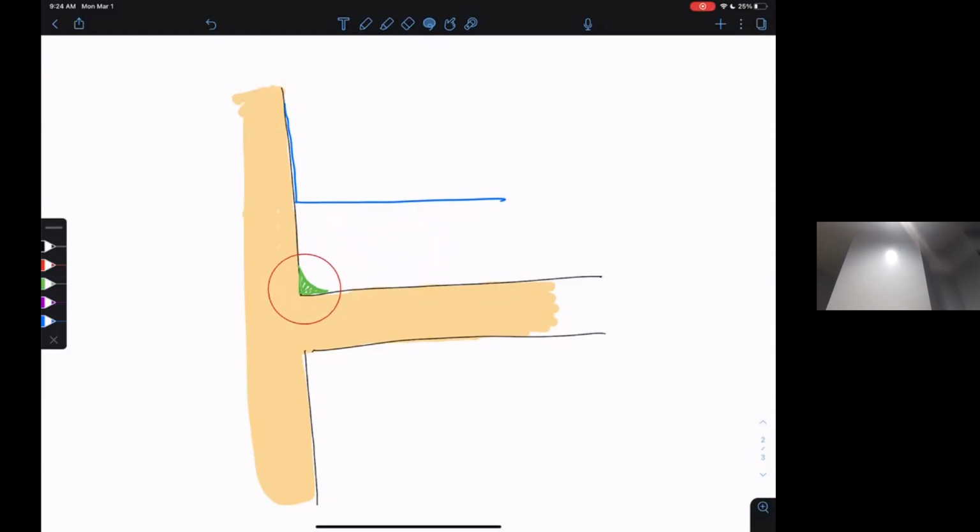A lot of people think, why don't we just center it right on the corner? So we say, this circle center is right here. And that would totally work. But remember, these bits are cutting sideways. I couldn't get the bit to this location. Why not? Because if it was cutting sideways, you're going to tell it, here, cut this shape out.